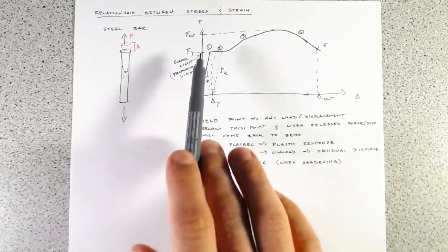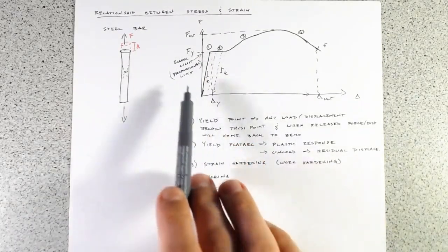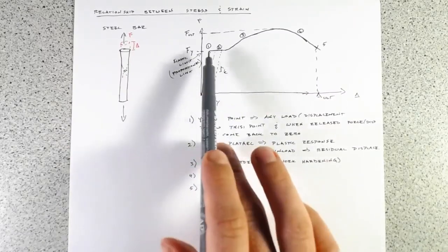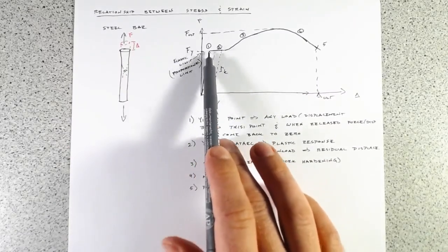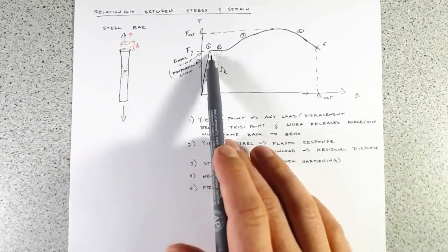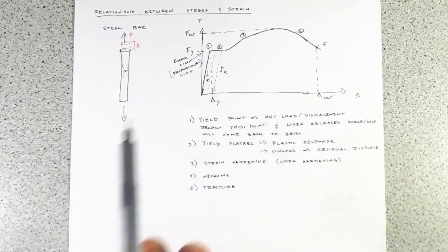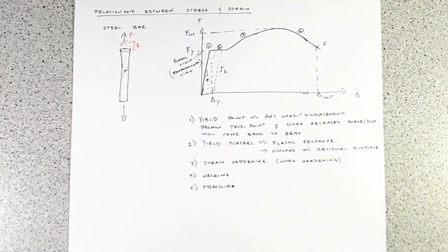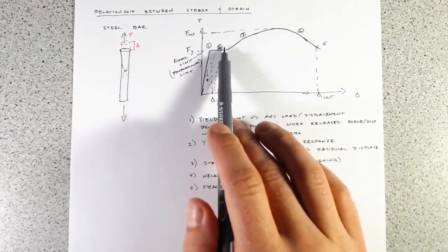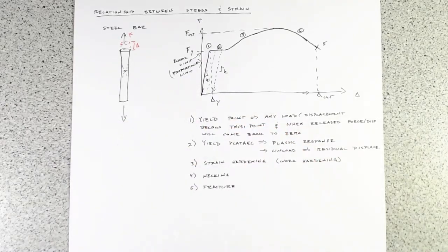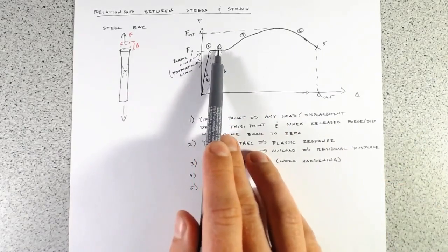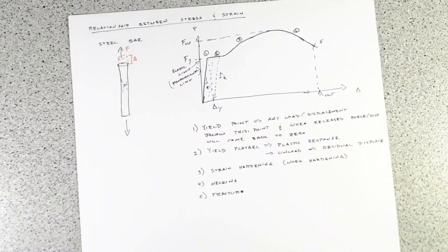So the only thing that's going to line up is our Fy and our delta y. That's why there's a proportional limit. This is why this is a really special point, because any loads below this level, when we unload it, we return back to zero deformation. So that's our elastic design. Anything up here is plastic, and so for our limit state design, we're designing right on this level of plasticity.